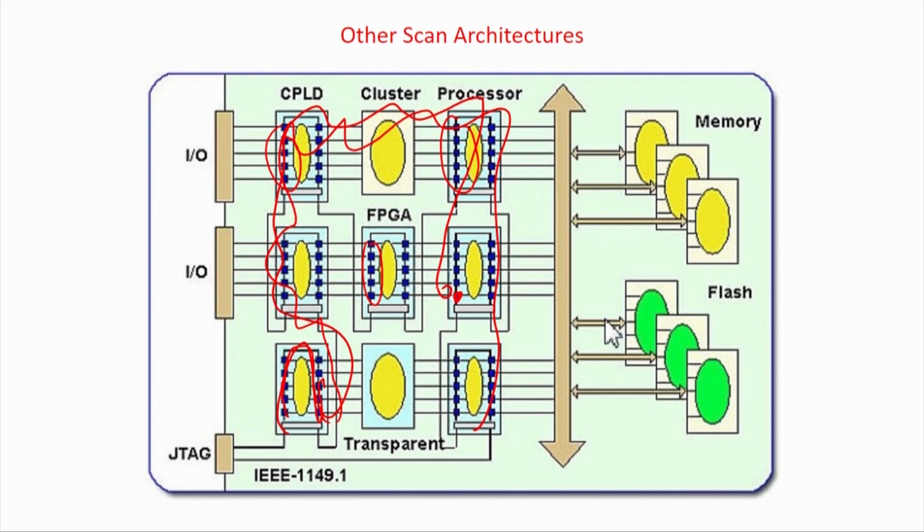So this is similar, except that instead of a single circuit, the whole concept is a board. Instead of a flip-flop, the circuit has become your flop. This is a board and these are your chips. This concept of scan chain is called boundary scan. It is very synonymous with what we know about a normal scan chain. If this is not a board but an IC, then you can think of this point as a flip-flop. You cannot control it directly, so you use a scan chain. But when this same thing is mapped to a board with a lot of ICs, we call it boundary scan, and we call it 1149.1.